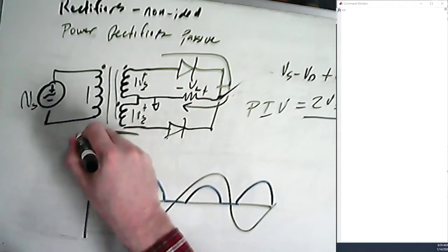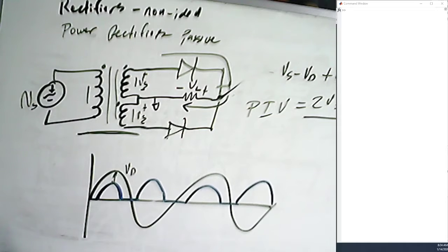Another disadvantage of this one is we do need a transformer. There's no way to do it off of a non-transformer model. You have to have some kind of center tapped or three taps on your voltage somehow. So we certainly do need that in order for that to work. Most configurations we want that anyways.